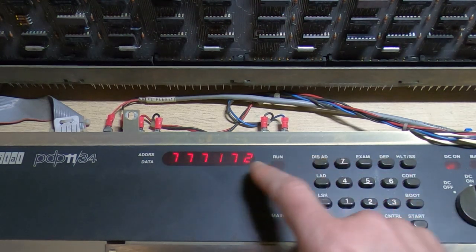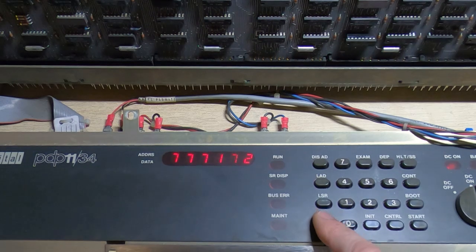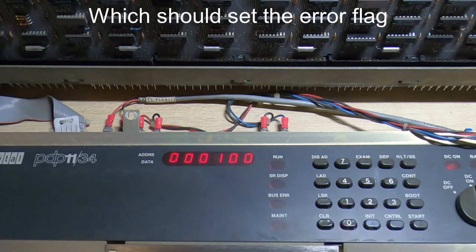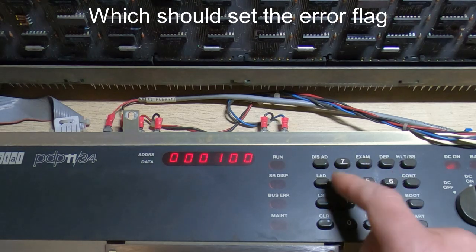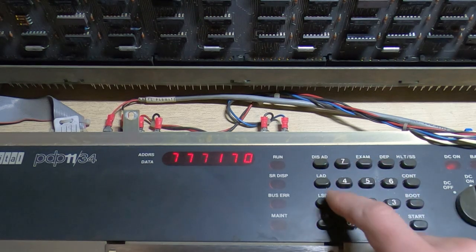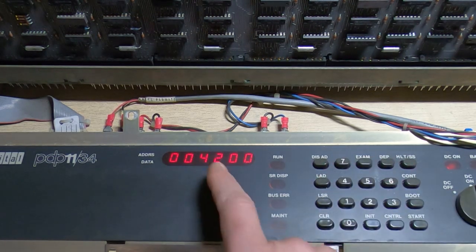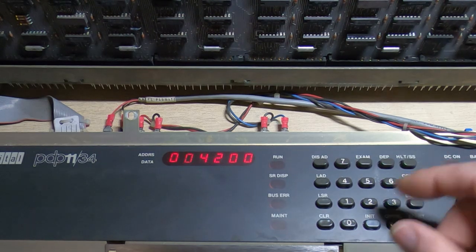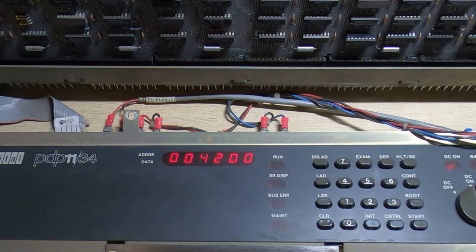Go to the next register at 172, we'll send a value of 100, deposit that, and we'll now go back to the first register again and examine this, and again the TR bit is set, which is good. It means it's accepted the command.